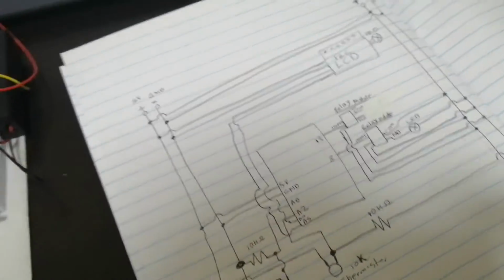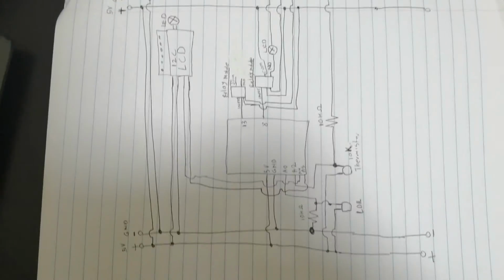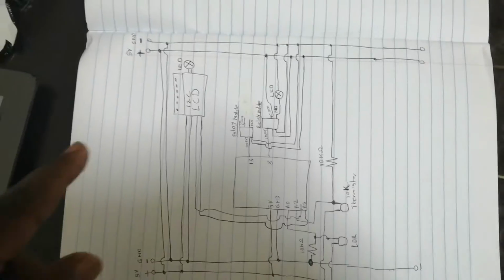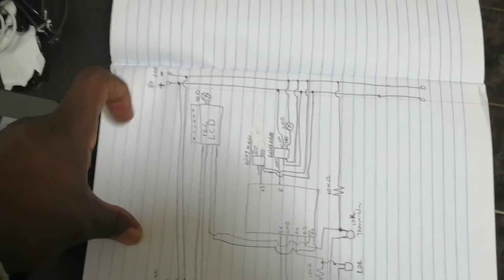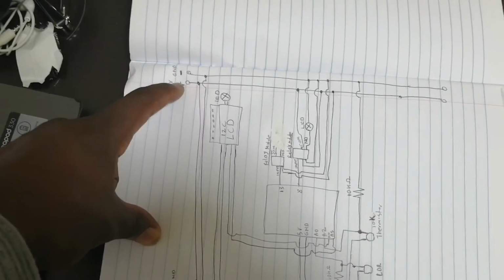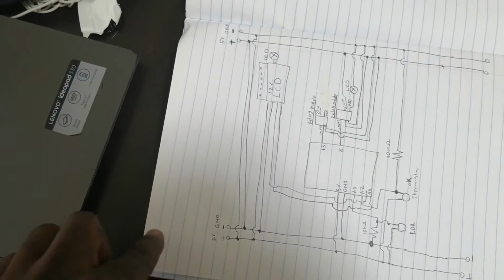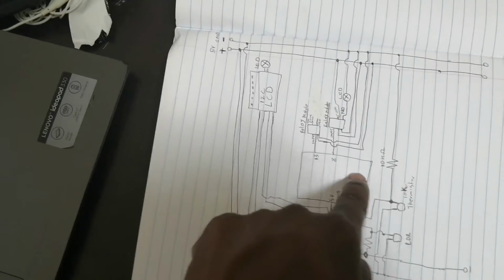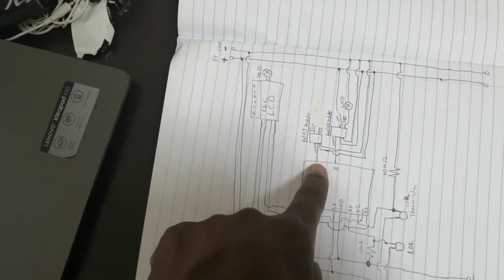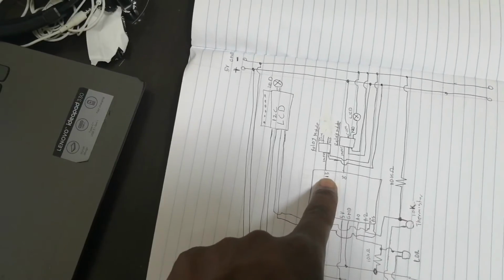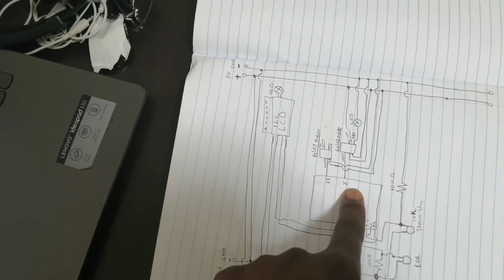And then right here is my schematic. If you want to connect it on your own using that code, this is basically what you're gonna do. This is just basically your breadboard. Your positive line and your ground, then the other side also a positive line and the ground. And this is basically your Arduino. This is output number 13, this is output number 8 according to my code.